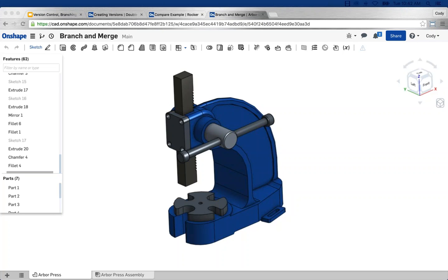Good question. When you copy the tab to another document, will the branch also be copied? It copies the active. It does not copy the branches of that part, for example. It's very similar to the copy workspace, essentially. So when you copy a tab using the right-click copy to clipboard, it does not copy all the different branches of the part, only the active.